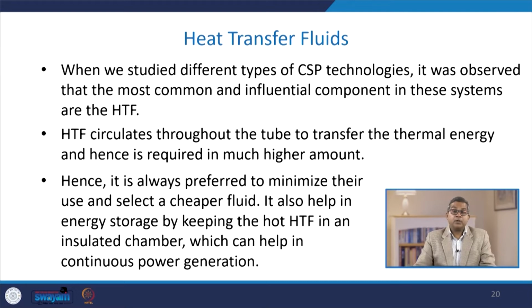We may have a debatable thing on this cheaper fluid. Sometimes the cheaper fluid may have a corrosive effect. So while adopting this economical approach, one must look at different parameters, maybe which kind of fluid to be used. It should be non-corrosive, non-reactive, it can recirculate easily, and it can discharge the heat to the point as quickly as possible. So all these things must be addressed. These heat transfer fluids also help in energy storage by keeping the hot heat transfer fluid in an insulated chamber, which can help in continuous power generation.